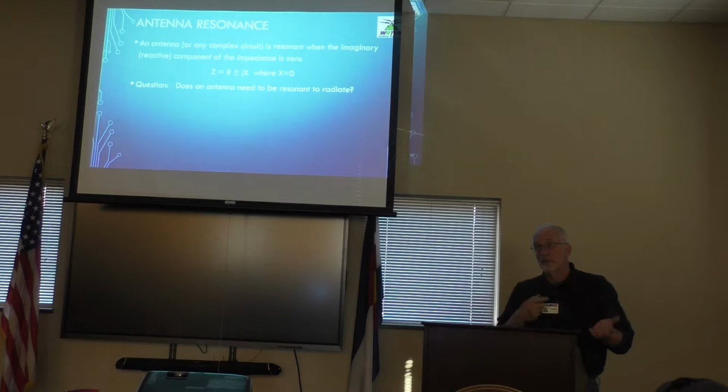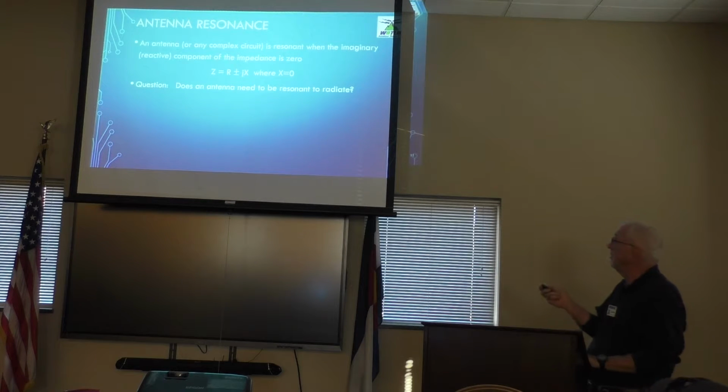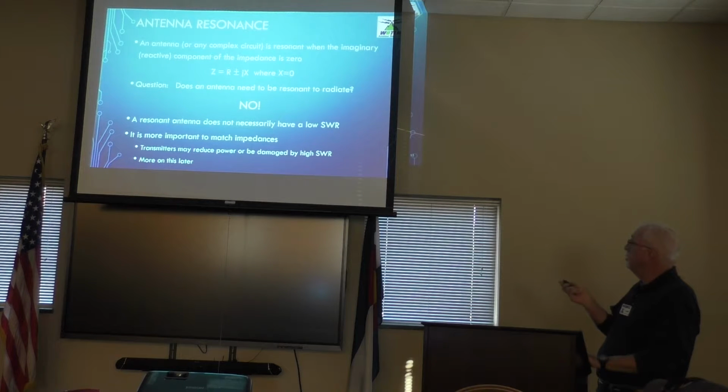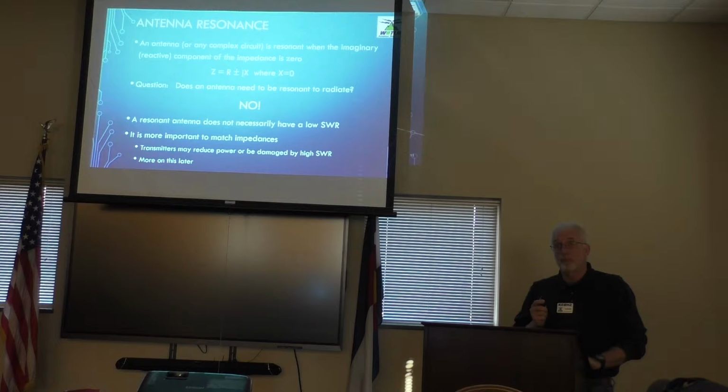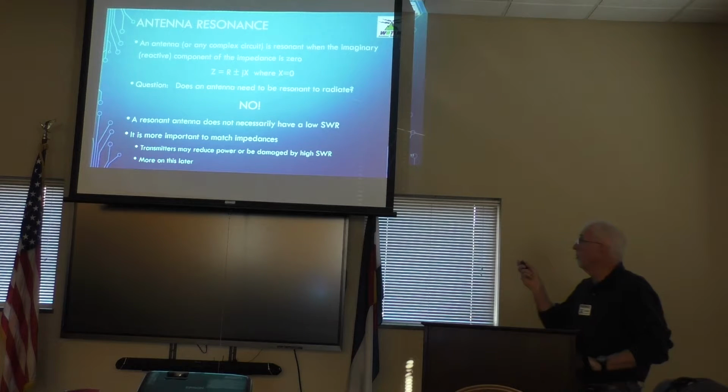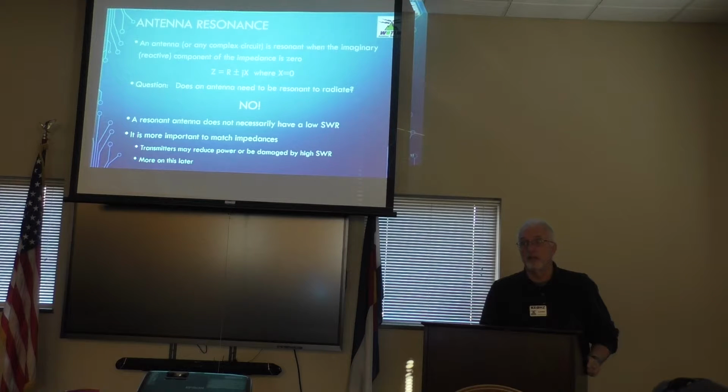Well, that doesn't translate to propagation. What it translates to is impedance matching that we'll talk a little bit about later on. So no, a resonant antenna does not even necessarily have a low SWR. We'll talk more about SWR. But we frequently hear, and I've seen these on YouTube videos, somebody talking about, we've got to get it resonant to lower your SWR.